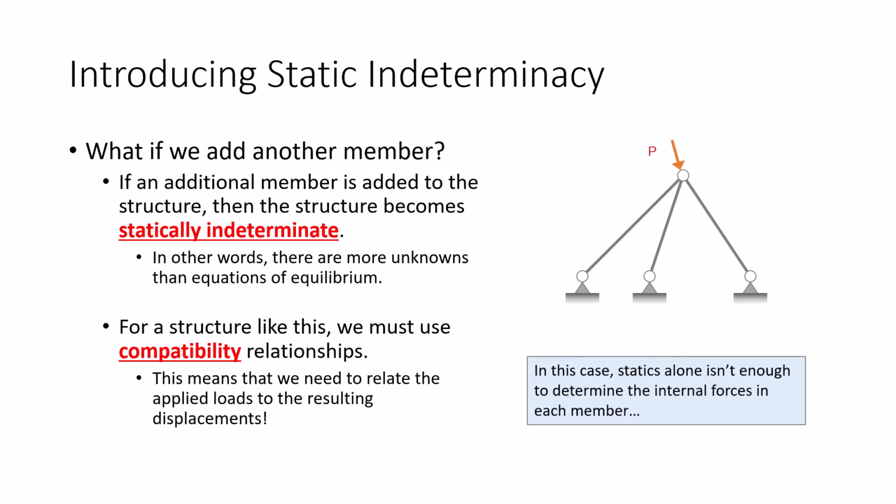What we learn in here, however, is what affords us to solve this. Basically, what we're using is what's called a compatibility relationship. In other words, we relate the applied loads to the resulting deformations. The idea is that those deformations, after the load is applied, must be compatible.